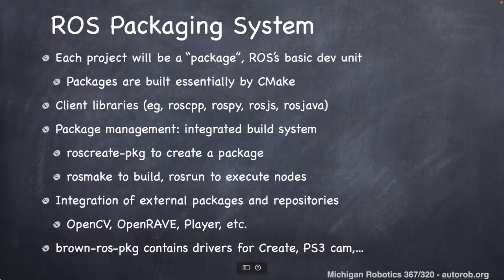And within these packages, you'll have access to client libraries, so roscpp, rospy, and so forth. The actual management of the package is going to be handled by an integrated build system within ROS. So you can rely on some built-in tools within ROS to help set up the packages, to build the packages, and to execute the packages once they've been built. Once again, these packages support external libraries that you could use, so OpenCV, for example, or TensorFlow. These can be integrated with these packages.